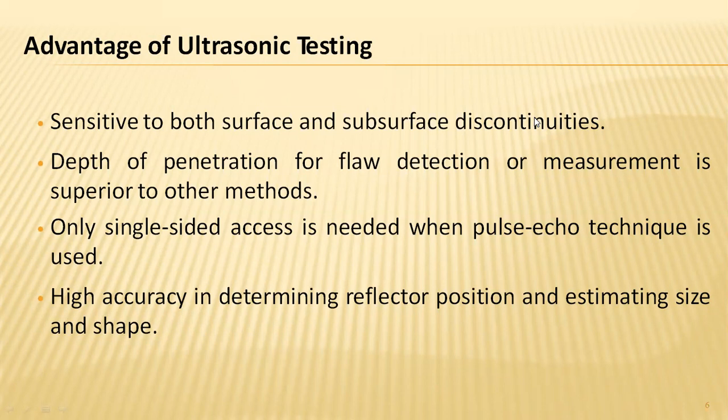In almost all the strategies, it has its own way of examining the overall properties and defects within the objects. And one more strategy: only single-sided access is needed when the pulse echo technique is used.